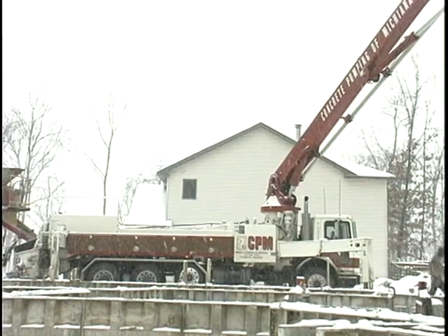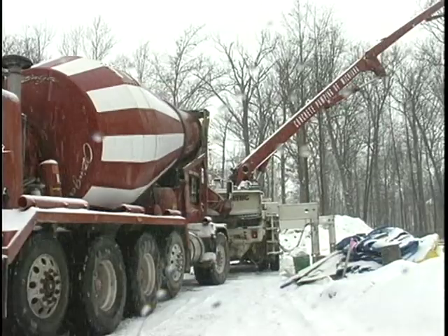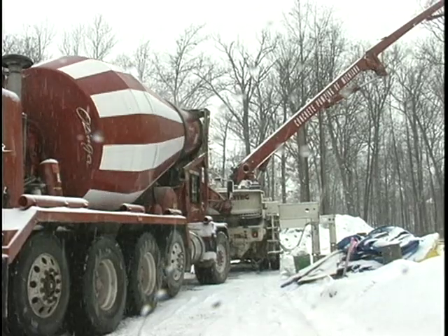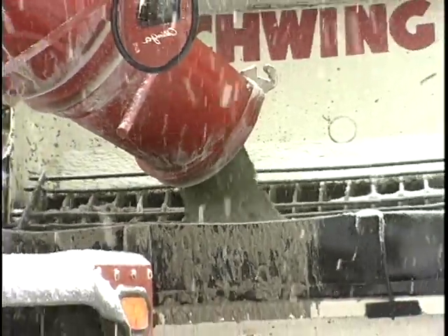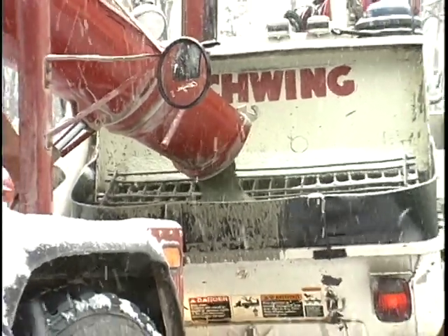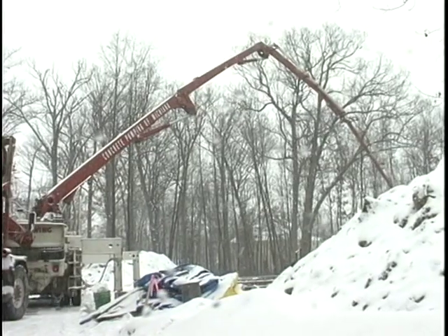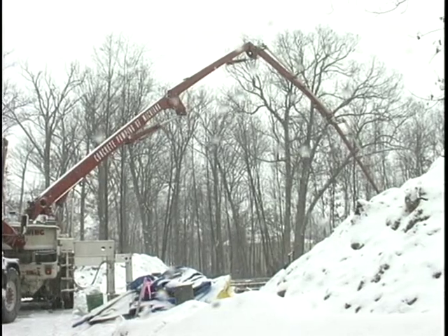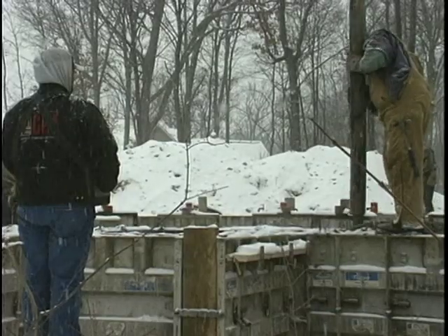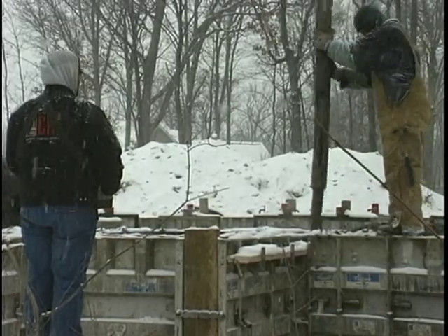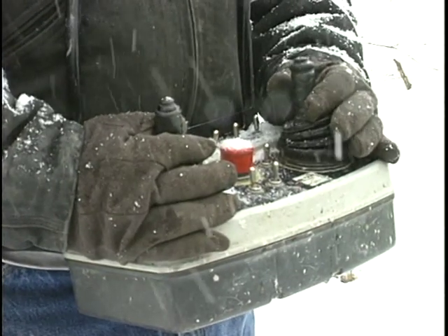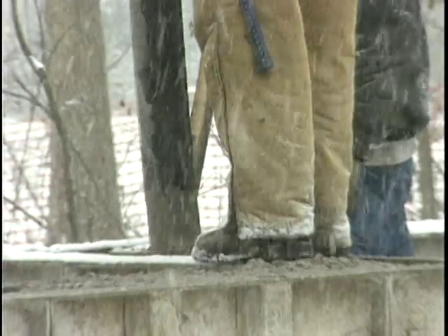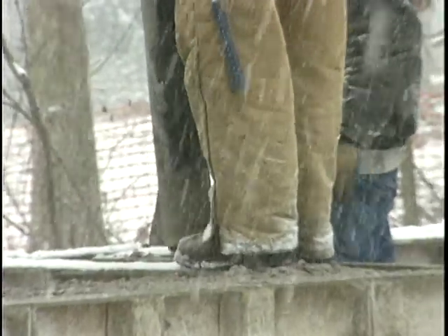If the concrete mixer truck cannot reach all the way around to pour the foundation, a concrete pumper truck is often used. The mixer truck pours its load into the back of the pumper truck. Then, the pumper forces the concrete through a long hydraulically actuated boom. A remote control unit is sometimes used so that the operator of the pumper truck can stand next to the nozzle to monitor concrete flow into the foundation wall forms.